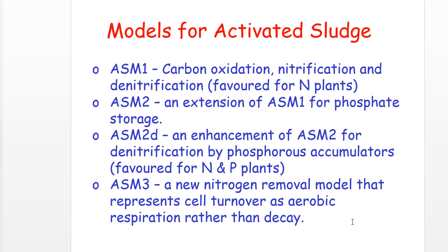First of all, where most of the work has been going in is activated sludge, since that's the most applied biological process for wastewater treatment. It started out with Activated Sludge Model number 1, mainly looking at carbon oxidation, nitrification, and denitrification.